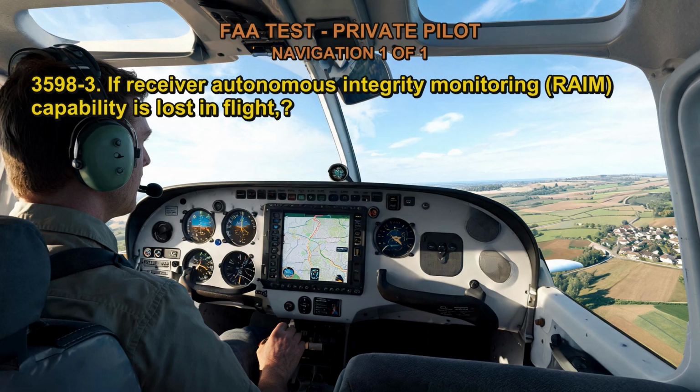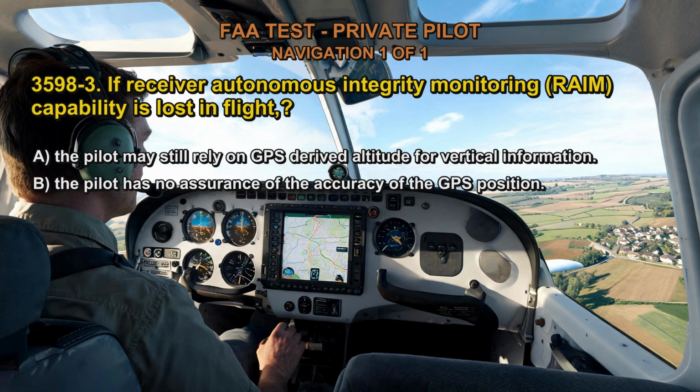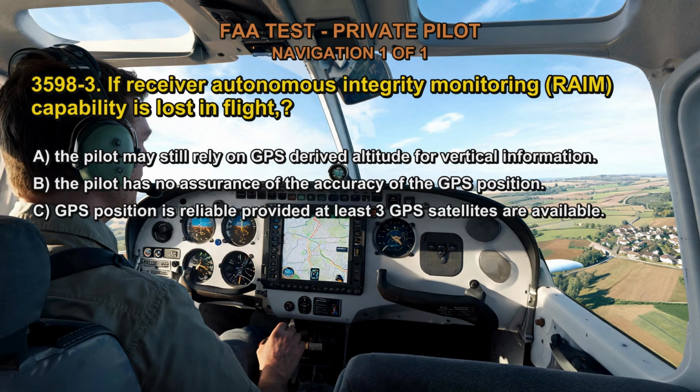3598-3. If receiver autonomous integrity monitoring, or RAIM, capability is lost in flight, A. The pilot may still rely on GPS-derived altitude for vertical information. B. The pilot has no assurance of the accuracy of the GPS position. C. GPS position is reliable provided at least 3 GPS satellites are available. The correct answer is B.